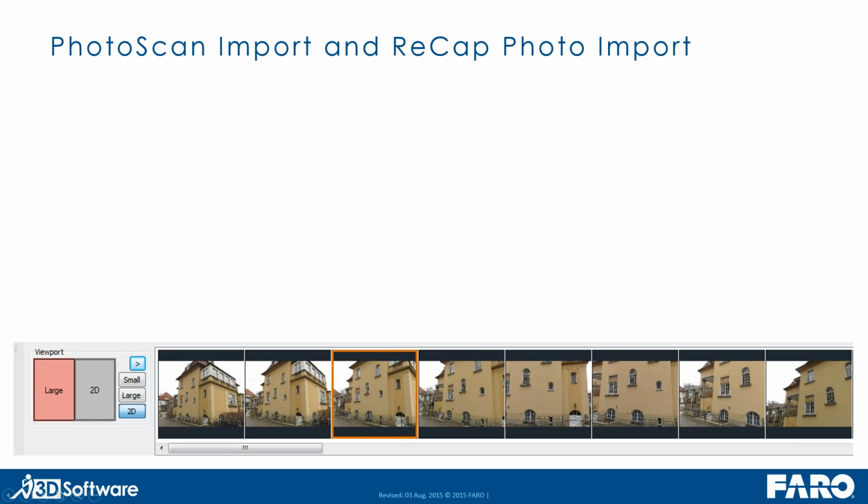The tools that we are using to get those results are, first of all, you would need to orient images, and PhotoPlan does provide tools for manually orienting photographs. You would need 9 control points per image.